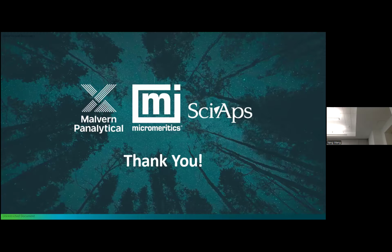is the instrument that I showed. The FT4 does like 7 or 8 different tests. Some of them are bulk properties, some of them are air permeability, compaction, all these different things. And the way that works is it's not just one measurement. You take measurements of different materials and you can look at the behaviors and say, okay, which attribute, the feature that I'm measuring, whether this is compaction or the permeability or flowability and things like that.